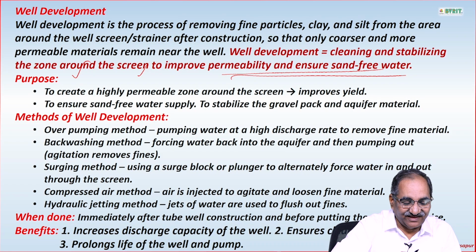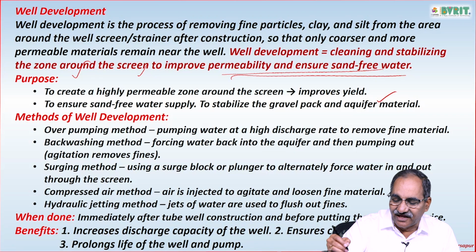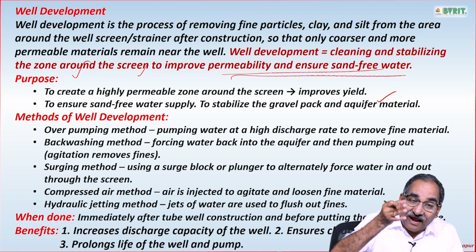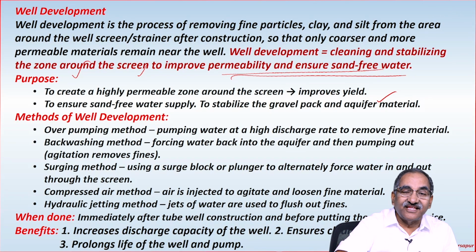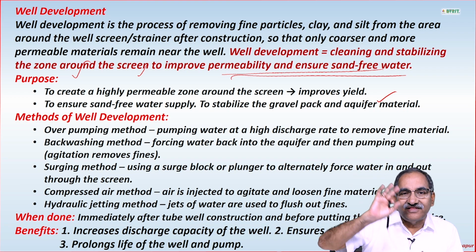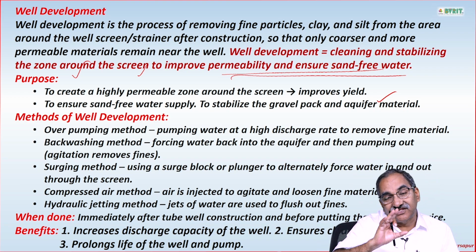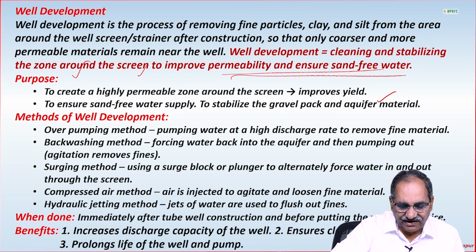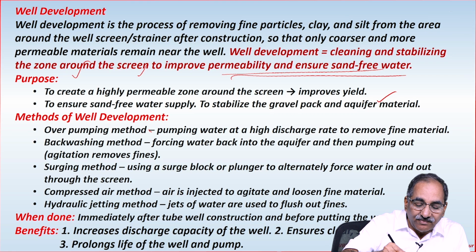That is the fundamental thing: to ensure sand-free water supply, to stabilize the gravel pack and aquifer material. Anyhow, well shrouding means to fill the gravel pack. But once packed, after some time the gravel pack naturally gets filled with sand particles. Cleaning all that and making that zone free of sand particles is what we call well development.